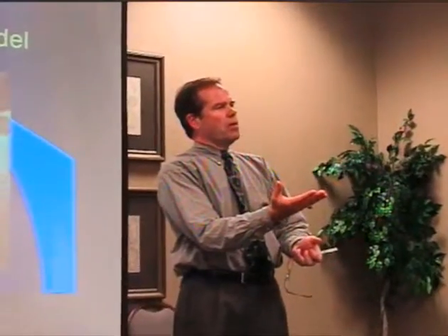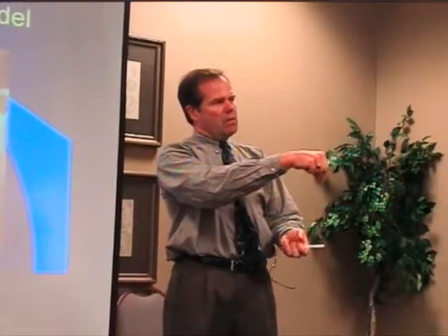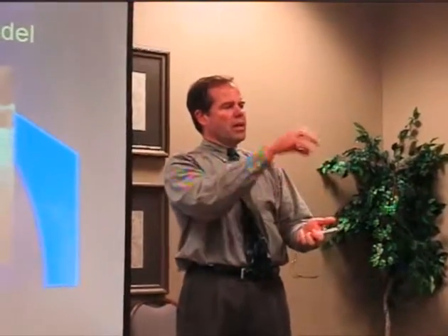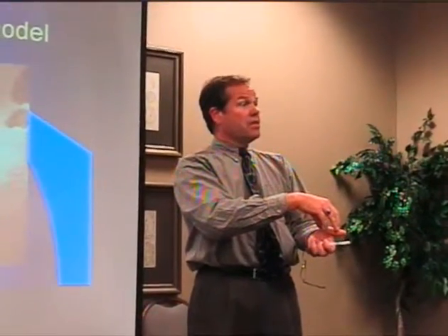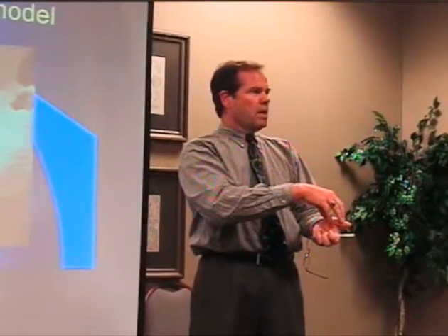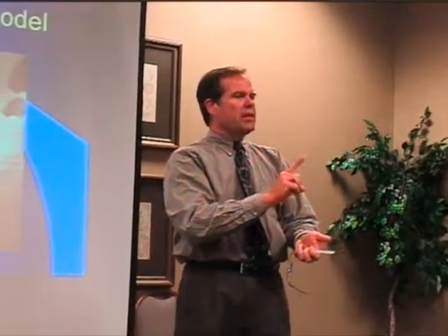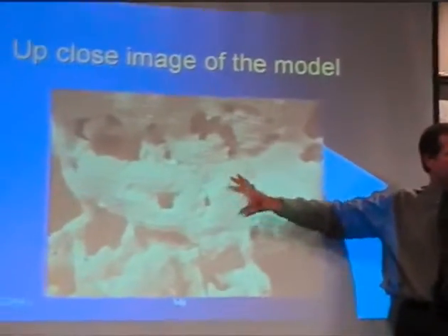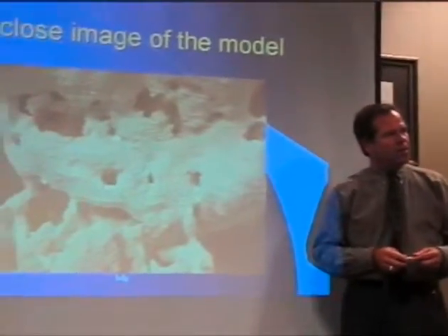Okay. I'm curious, from a practical perspective, how many layers is that, and how long did it take you to create that? This was made, I think, overnight. Like 4 to 8 hours. This is a little bit faster than stereolithography. In stereolithography, you do the same thing, except you have a pool of polymer, and you polymerize it with a laser beam hitting it. So this is done by spray coating an adhesive, and it's faster. It's not quite as detailed, but at least for a first look, I think this would be enough to show you have something close to that.